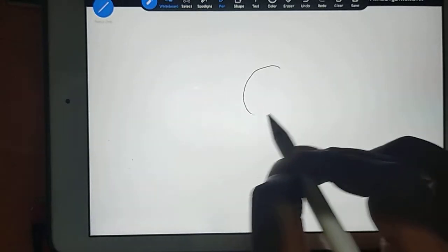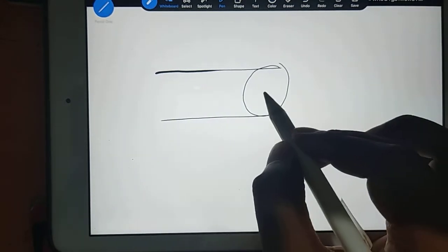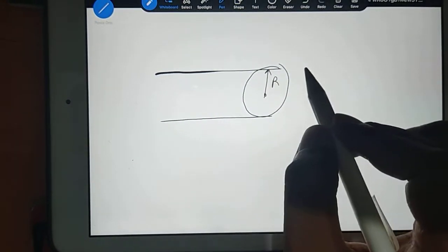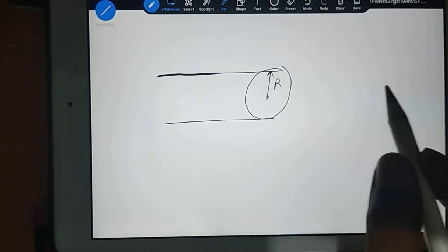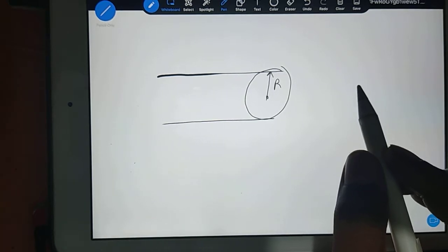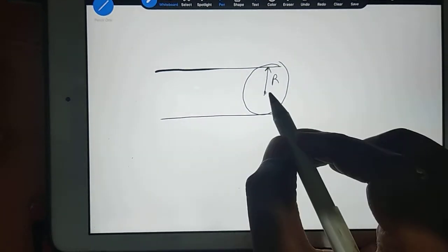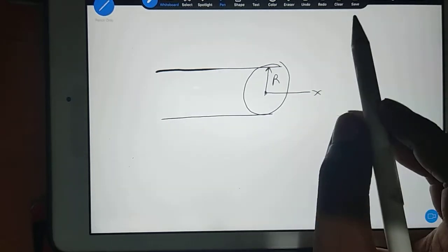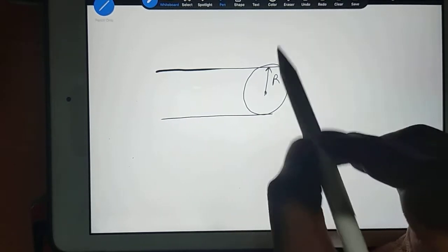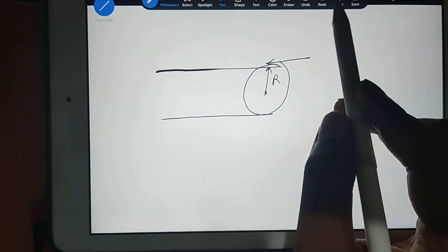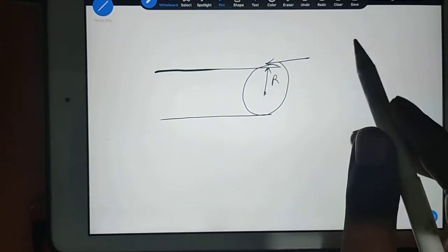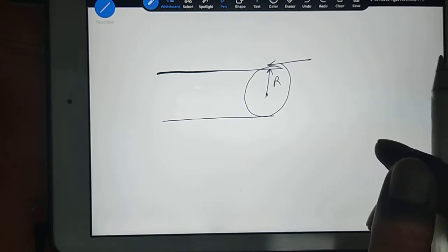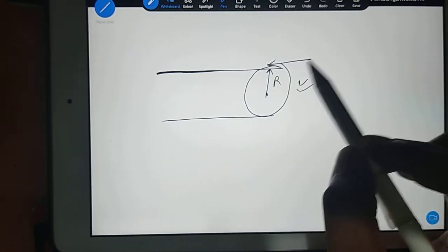Suppose you have a shaft here. When you apply torque on the shaft at radius r, if you have revised the chapter, then you should know that a shear stress variation is there. At the center you will have some shear stress, and here you will have some other shear stress. So the shear stress is varying, which means it is not constant. How will you know how much shear stress we are getting, and how to account for the variation of shear stress? For all those things you revise, because it is a detailed lecture I have given.